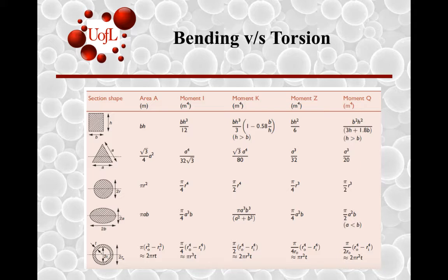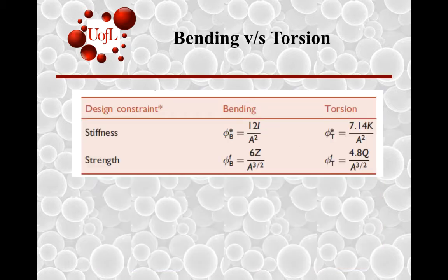Effectively, instead of tensile strength, you come across shear strength as the material property of interest. Shear strength and tensile strength are related to each other in most cases. Roughly, shear strength is half of the tensile strength. And so typically in a handbook or a material database, you're more likely to come across tensile strength compared to shear strength. And so accordingly, you can estimate the shear strength in this case, which is of importance for a torsional loading. In that manner, you can begin to estimate shape efficiency factors for torsional loading, right?